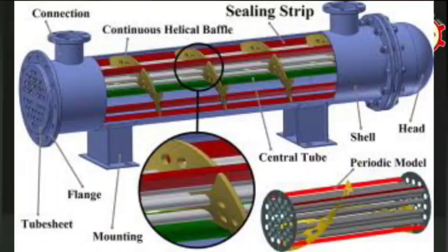We can do one more thing. We mark the baffle where it will be located on the shell side and cut the shell, remove and cut the baffle, and re-weld the nozzle with an insert plate. No, cutting the baffle and the shell at every place, I think, is not advisable. No, we marked it up in CAD. It is acceptable. We can do it.